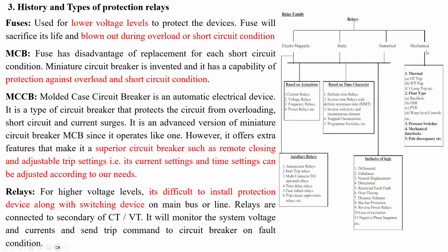And mechanical relays are mainly used in transformers, where you are identifying the Buchholz conditions, winding temperatures, as well as oil temperatures. For this, we are using thermal relays as well as other mechanical relays.